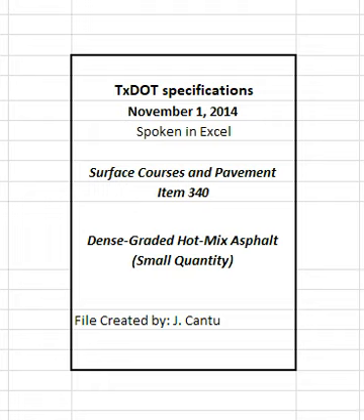2.6.1 Lime and liquid anti-stripping agent. When lime or a liquid anti-stripping agent is used, add in accordance with item 301, asphalt anti-stripping agents. Do not add lime directly into the mixing drum of any plant where lime is removed through the exhaust stream unless the plant has a baghouse or dust collection system that reintroduces the lime into the drum.